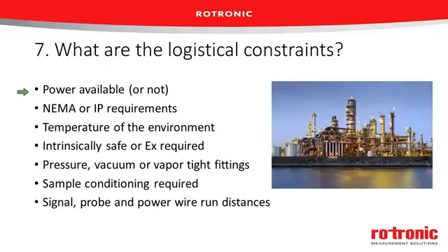The vast majority of these instruments are going to require some type of power, whether that be AC line voltage or battery operated. This is an important consideration. I've seen in many situations, especially in large warehouses, where people are looking to monitor those, the cost of running the data lines and the power lines can easily exceed the cost of the measurement instrument itself. So this can really drive you into saying, I want something that runs on AC voltage or is battery operated, or potentially something that's got a bit of both. So it runs on the line voltage regularly, but it's got battery backup in the case of a power outage.